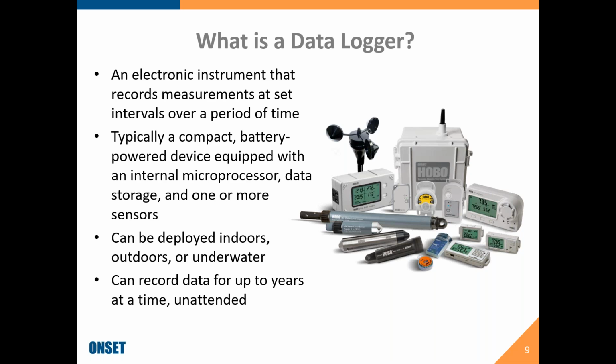So first of all, what is a data logger? I used to joke it was a conversation stopper at first. What is a data logger? So it is an electronic instrument. It's going to record at a set time and date that you select over a period of time. It's typically a small battery operated device, and it has an internal microprocessor, data storage, and one or more sensors.